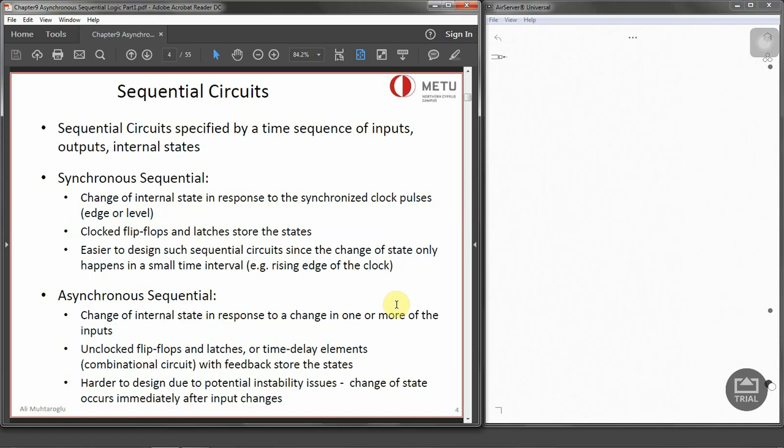Or in other cases, they are economical to use. They are small independent systems. They just require few components, without a clock generator, clock trees and clock wires around. And two synchronous circuits with independent clocks may need to communicate with each other. That's another problem, and that's why we might prefer to use asynchronous circuits.